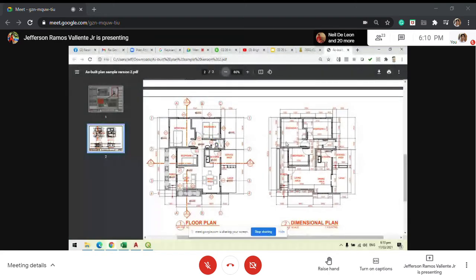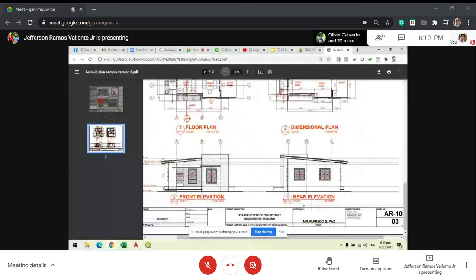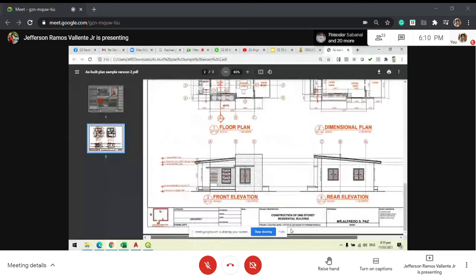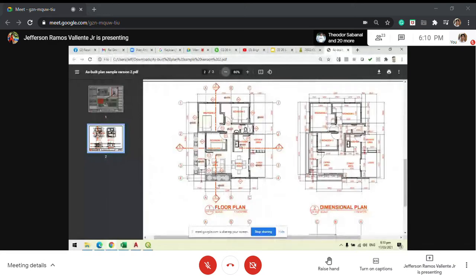Okay, none. For the as-built requirements on spacing, I need to see only 4 contents, just 4 since it's still basic. First is the floor plan. The floor plan should demonstrate the dimensions of the walls and their relative distances to each other. It should also show the location of the doors, like this one, D1 is door 1. Windows are abbreviated as W1.